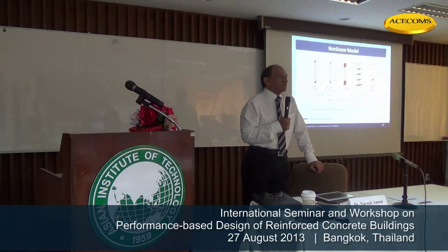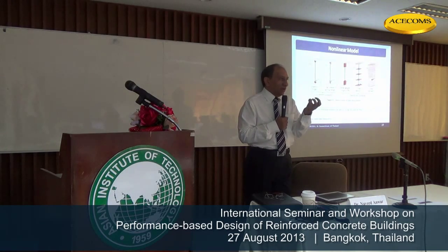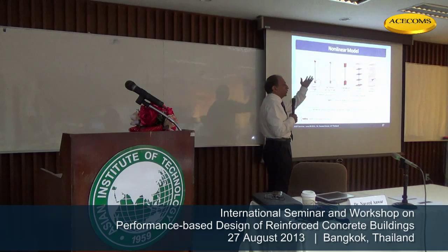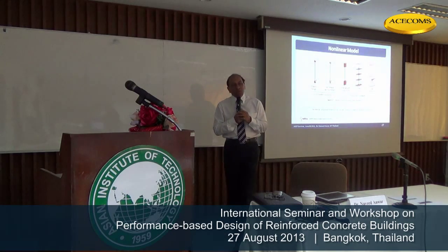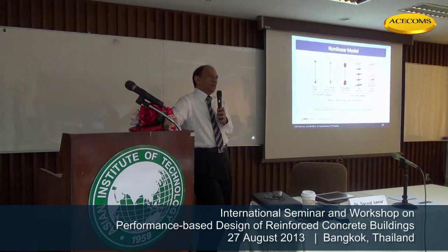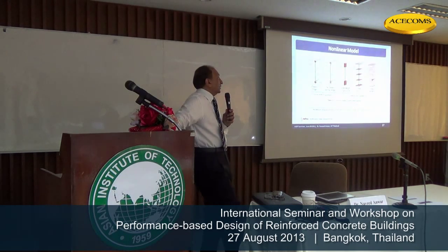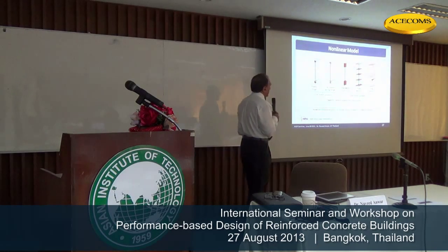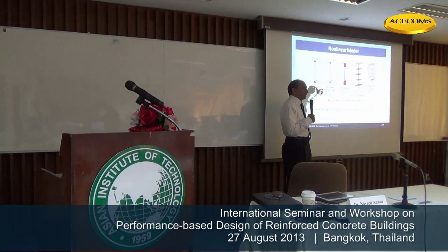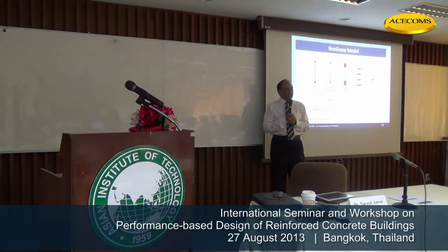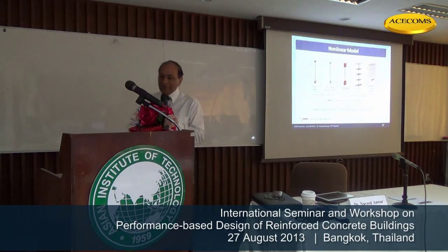So there is no simplification, no lumping of the nonlinearity, no need for a hinge zone, no need for a fiber model. You could directly use finite elements with nonlinear elements to model the structure. Of course, this is relatively new and people are getting used to it, but this can give us much better information than the lumped nonlinear model. So depending upon the software that you have, you can use plastic hinges, nonlinear links, finite length hinges, fiber sections, or finite elements. These are the primary tools that we have.